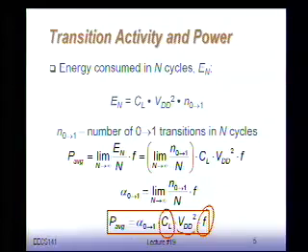It's a rare event that they switch. Think about it, they have a 10-input NAND gate. Right? The chances that I have a 0 to 1 transition are going to be fairly small. Because you look at an AND gate, you look at 10 inputs, that's 2 to the 10, that's a truth table of about 1,000 lines. There's only one line that is a 1.